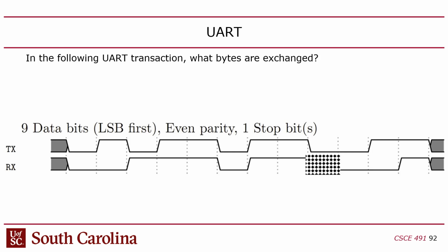Now in this case, I've got what's called an erasure, which is where there's an error here. If I'm a transmitter, then on my receive line I'm getting a signal back, and somehow I know that this bit is garbled. I know it's wrong. So the question is, can I figure out what that is? You can actually fix an erasure with a parity code.